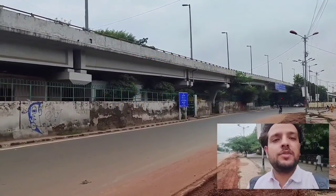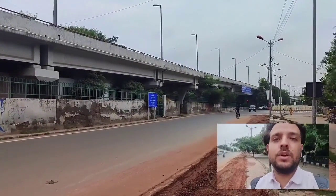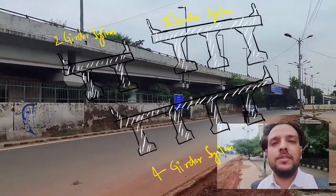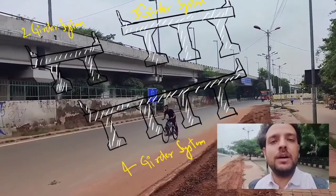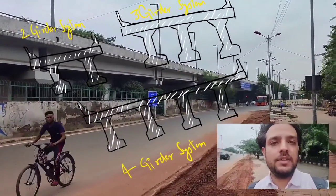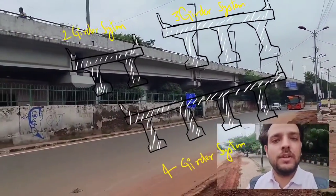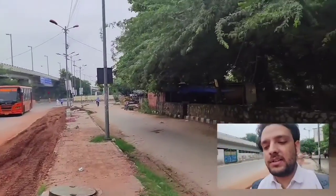Typically the spacing ranges between 2.8 to 3.2 meters, and 3 girder, 4 girder, and 5 girder systems are predominant in the bridge design industry based upon the total carriageway above. And you have to provide a minimum of 2 girders in any structure even if the total carriageway width above is very small. So this was another component we discussed: the spacing, and how the number of girders is decided.